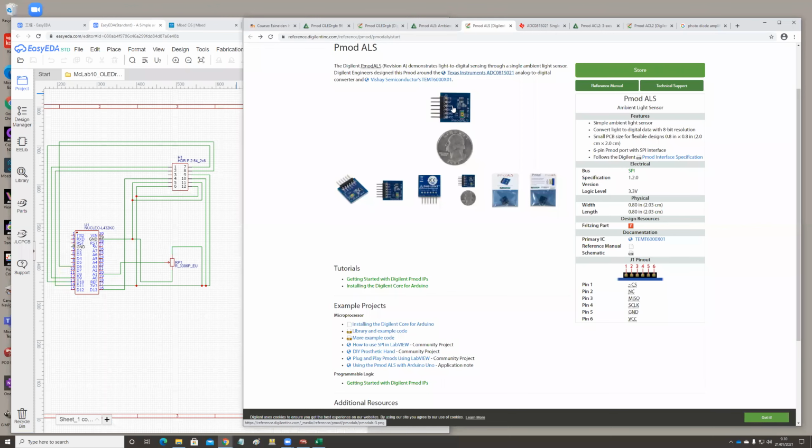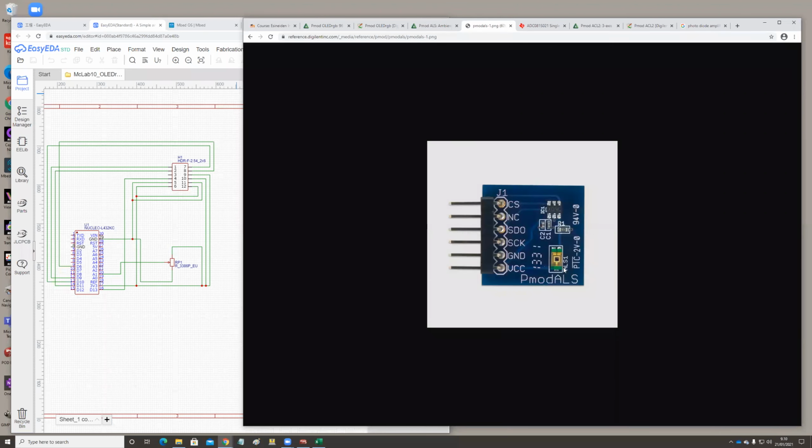So the right circuit is the photodiode, the ambient light sensor. There is the photodiode, there is the resistor, and then there are two capacitors to stabilize the voltages. And we measure the voltage over the resistor directly with an analog to digital converter. Light hitting the photodiode creates a few microampere current, and that few microamperes goes through a rather large resistor.